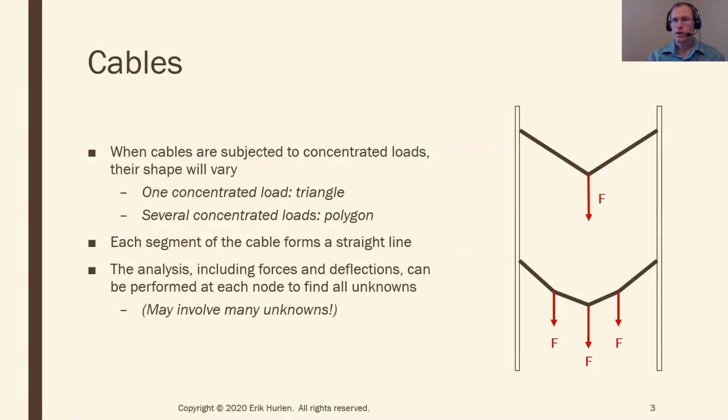If I have a concentrated load, and we've seen a couple of these, where I just have a force hanging down, that's going to change the shape of my cable. One concentrated load is going to make my cable look triangular essentially. So again, straight line segments for all my cables, and the tension force goes along those lines. If I have several forces, then I have several different pieces of triangles. Each segment of my cable is a straight line between all the forces, and tension forces go along those same directions.